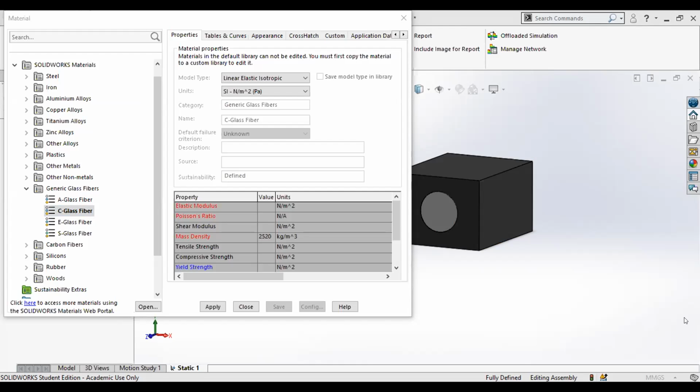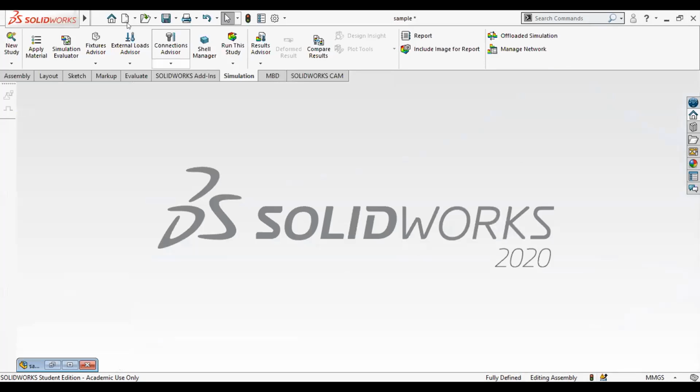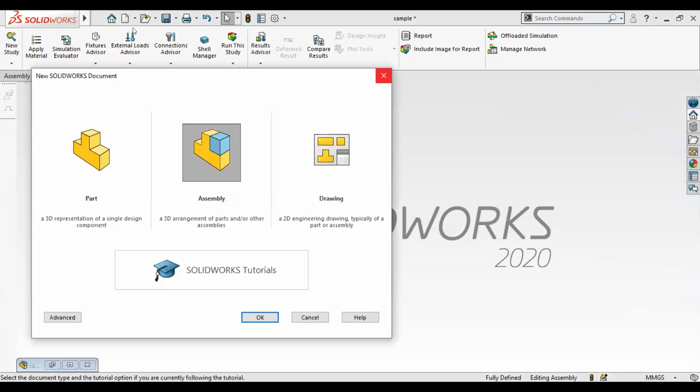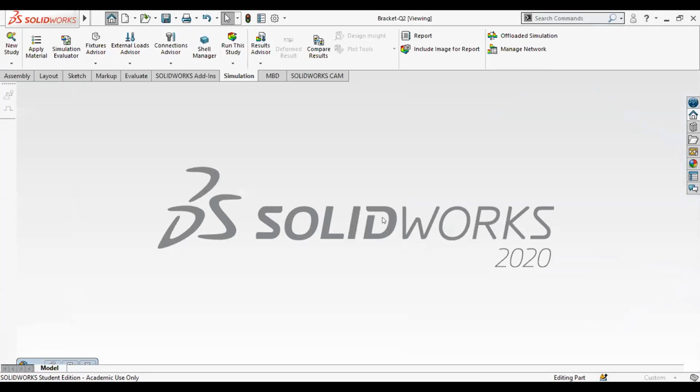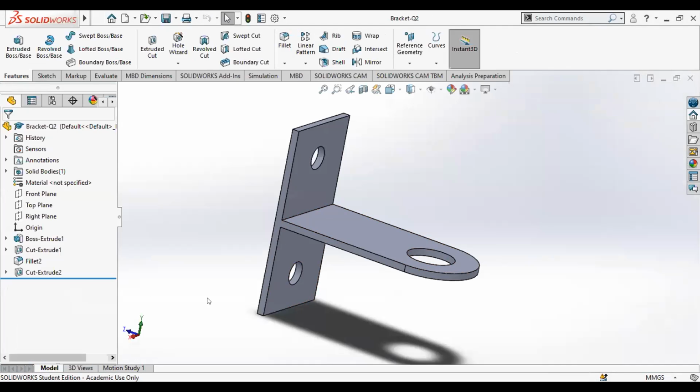You can do different types of analysis to check whether all these designs can achieve your goal or not. For example, what is the maximum external force applied, and what is the minimum or maximum yield strength. Just like the bracket example I showed you just now, the idea is similar. I designed this, so I apply stress to see whether it can withstand the load, because my goal is to know whether this bracket can withstand 10 kg or not.